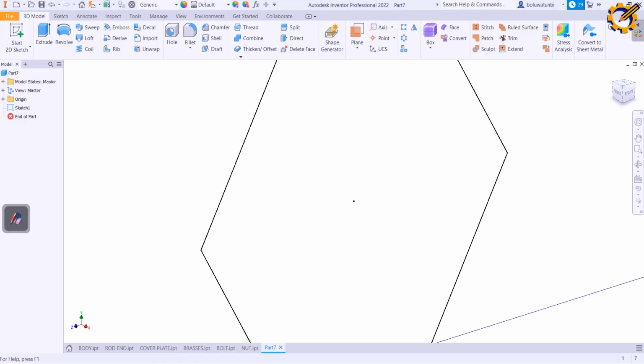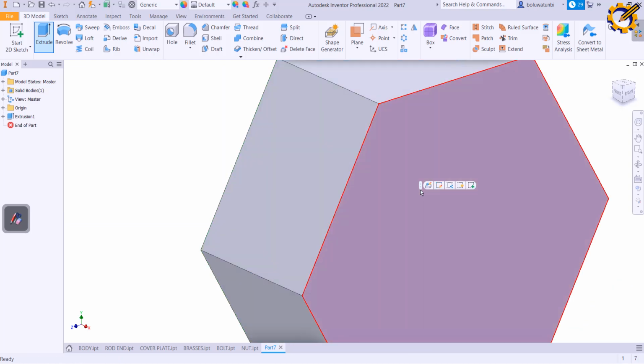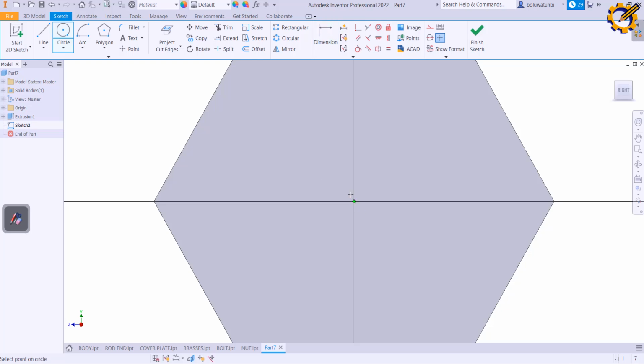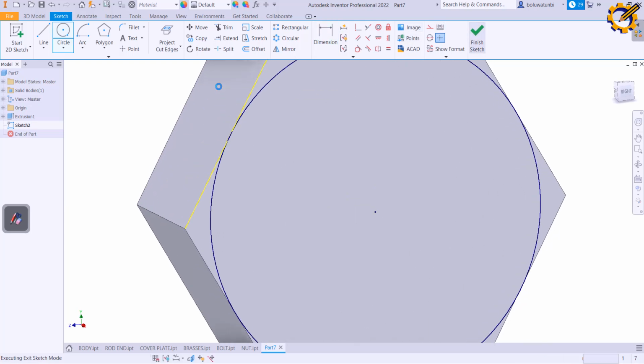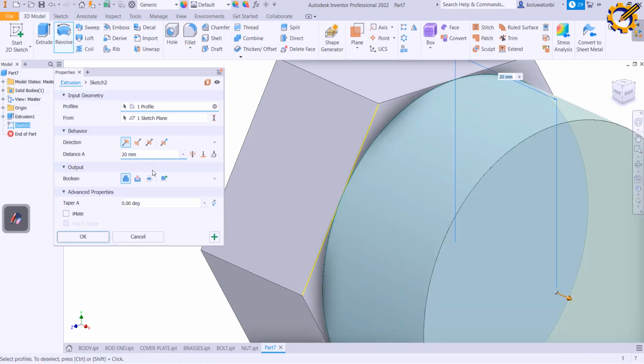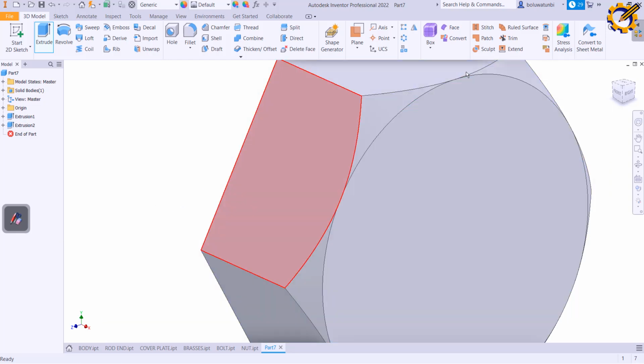And the thickness I'm going to extrude down to is thickness of 20. Extrude 20 on this face. A circle tangential to one of the sides there. Finish sketch. Sorry, it should be extrude intersect at 45. Enter.